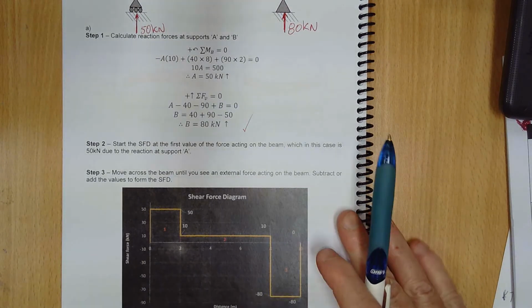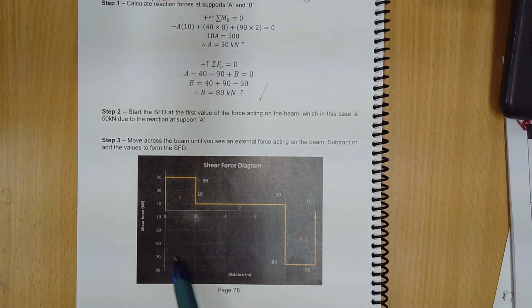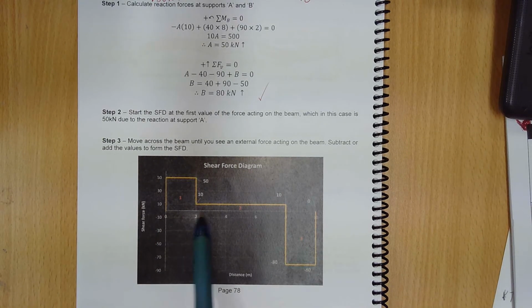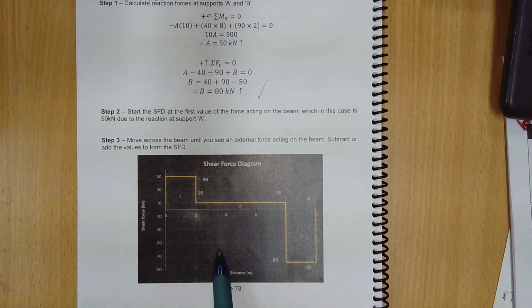So I suppose one of the first things we have to do, guys, is set up some sort of table. Now, if you're doing that on Word, it's very simple to just pop in a table and adjust the amount of columns that you're happy with and the scale that you're using. You can do a table and not use all the columns, that's fine, or you can sketch one up yourself. So here you can see along the x-axis we've got the distance in meters, and then the shear force in kilonewtons. Now these scales are independent of each other.